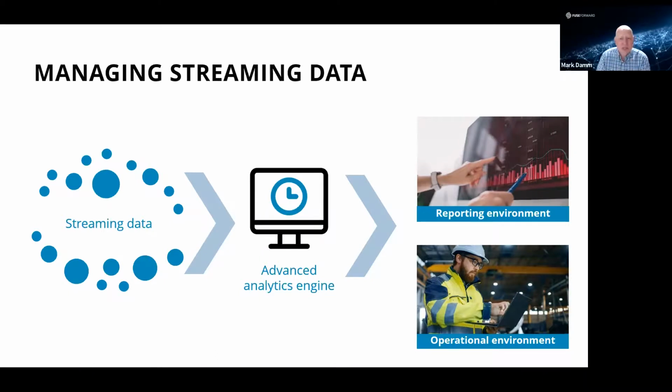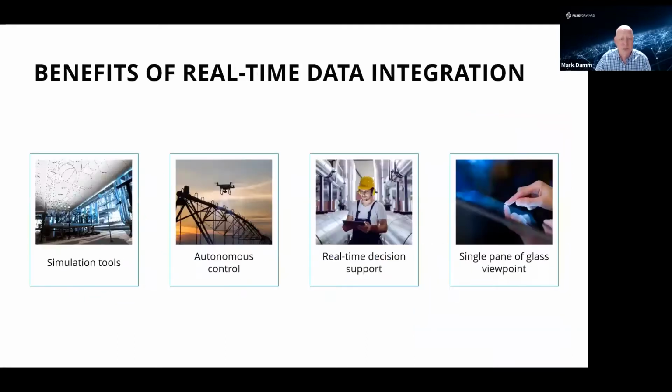And what it also starts helping us do is get into this real-time operational environment where we can start putting different kinds of operational dashboards in place for operators that are sitting in their control rooms. So what's the benefits of real-time integration? Well, I think of things like simulation tools. If I've got that and I'm an operator sitting behind my control desk, I want to be able to say, what if I changed the flow of this water pump and I started turning off these valves? What would be the implications of that? If I started to put this breaker on and closed down this transmission or distribution station, what would happen? That's a simulation tool.